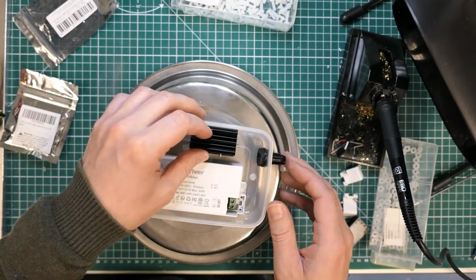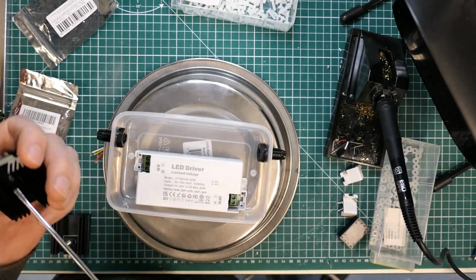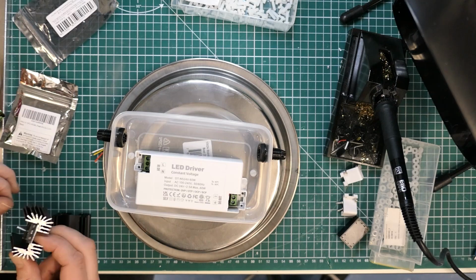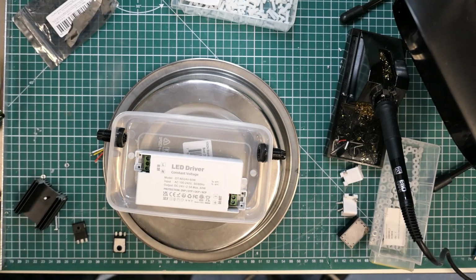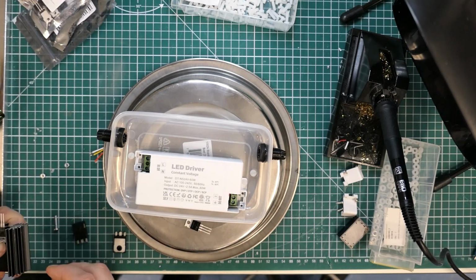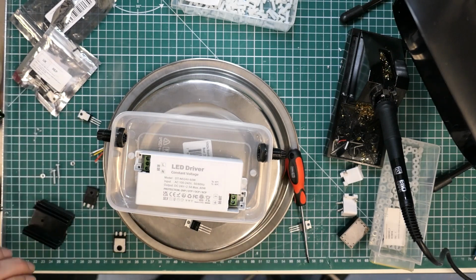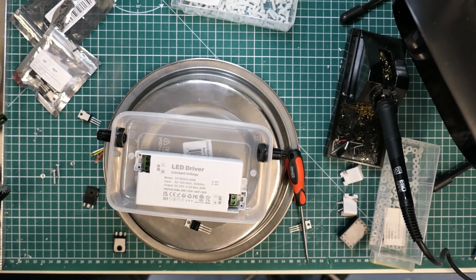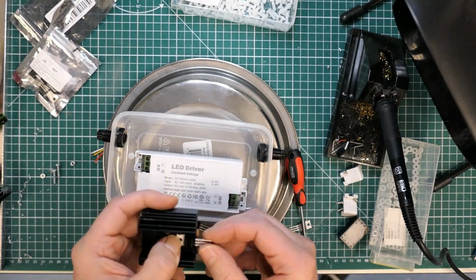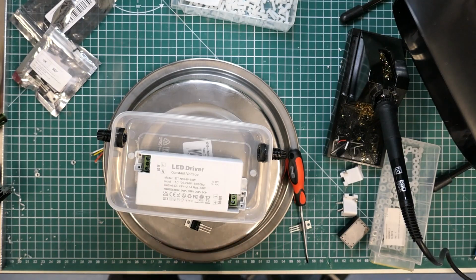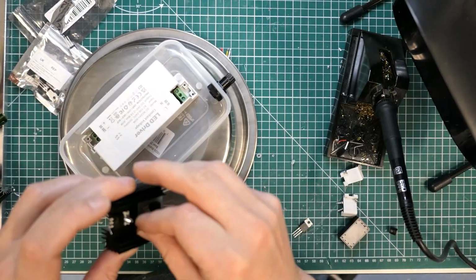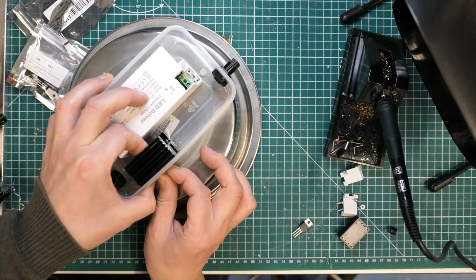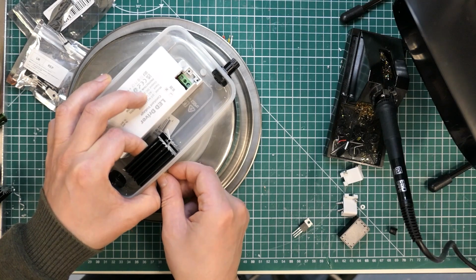Now I'm looking where we can mount the heatsink for the MOSFETs. So although the MOSFETs don't get hot, they do really need heat sinking because they just don't have any heat dissipation capacity at all with that tiny little metal tab. So they need mounting on a heat sink, but they can't just be directly connected to the metal because the metal tab is actually the drain of each MOSFET. So we need a little insulating pad that sits between the MOSFET and the heat sink. So I'm adding those now, and I'm trying to figure out exactly where this is going to go in the box. As you'll see, it's quite a tight squeeze in there.